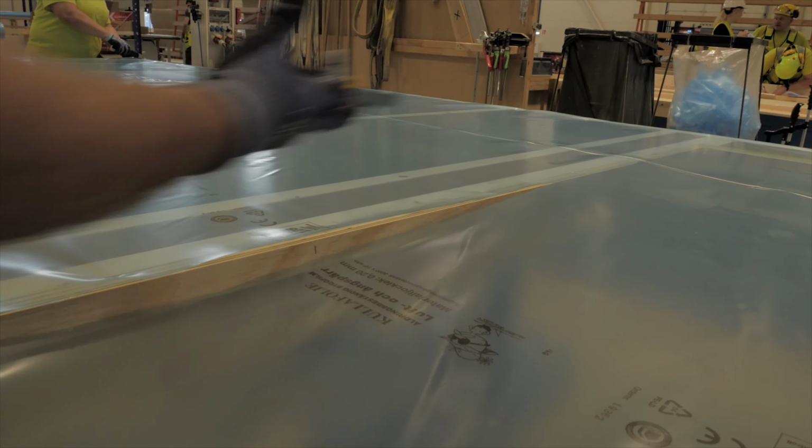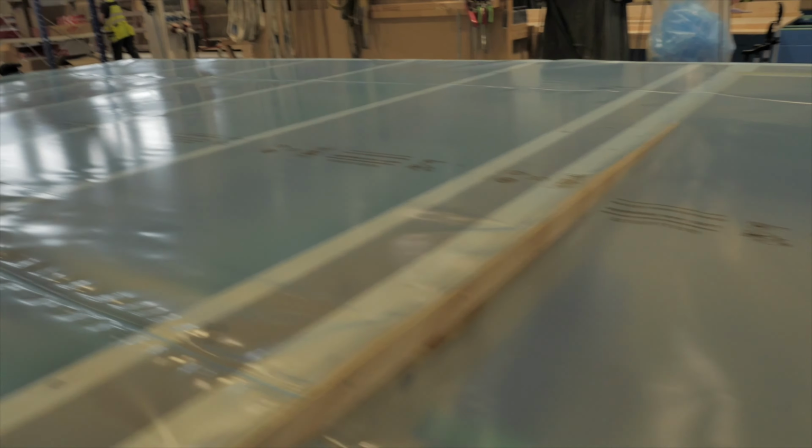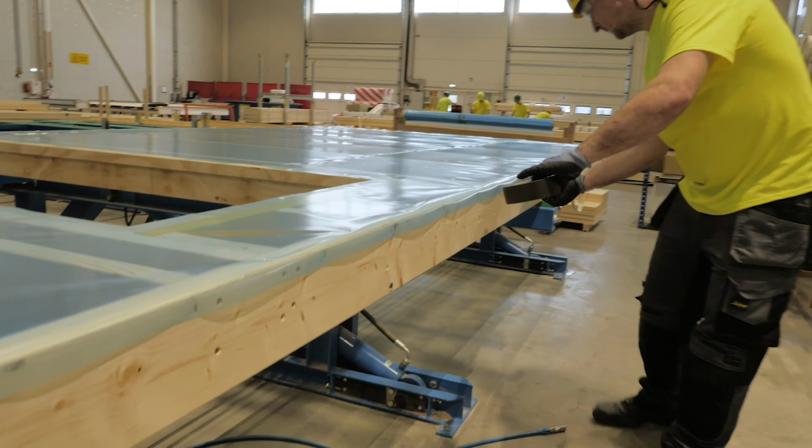Any excess material is cut off. As well, it also needs to be cut off around the wall openings, where windows or doors will be added later, and also secured with staples. If the vapor barrier sits tightly on the frame, it's important to seal all the overhangings and loose ends of the barrier by using tape. With this method, it is ensured that no moisture gets inside the frame.